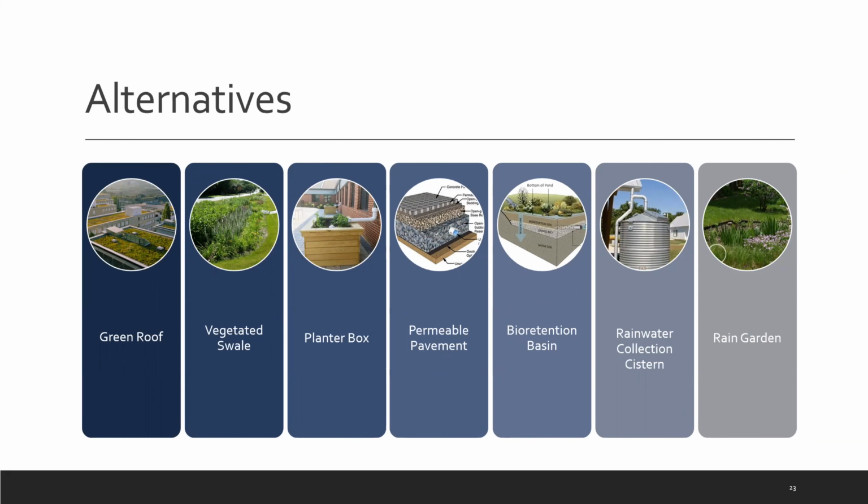These various LID design components may be implemented into the runoff management and treatment flow train design alternatives. Each of these components offers some increase in the time of concentration and attenuation of runoff on the site. They also have varying abilities to treat the water quality running off from the site.